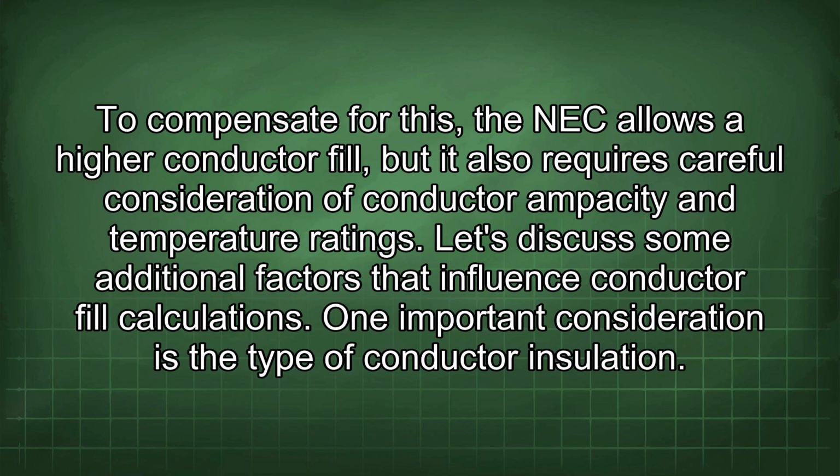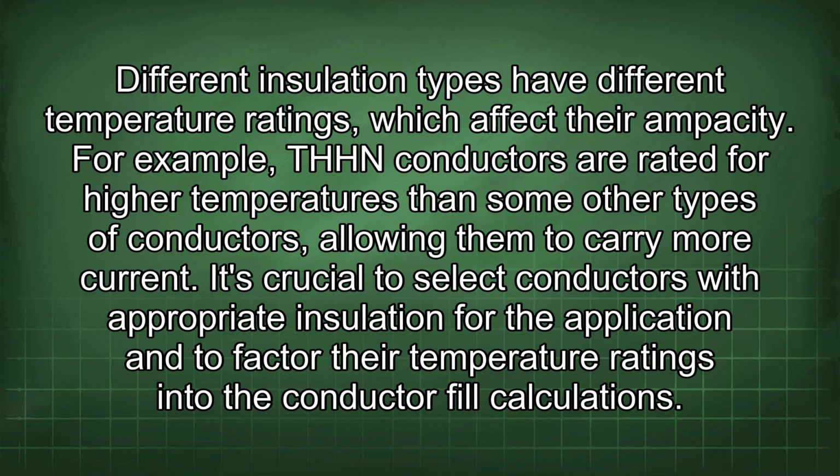Let's discuss some additional factors that influence conductor fill calculations. One important consideration is the type of conductor insulation. Different insulation types have different temperature ratings which affect their ampacity. For example, THHN conductors are rated for higher temperatures than some other types of conductors, allowing them to carry more current. It's crucial to select conductors with appropriate insulation for the application and to factor their temperature ratings into the